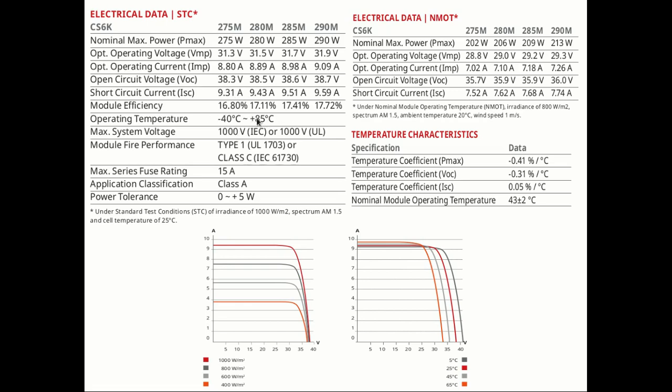Now, some of the other stuff we will not really use. These five are the most important. That is maximum power point, voltage at maximum power point, current at maximum power point, and even more important than that are the open circuit voltage and the short circuit current. We will need these last two, that is open circuit voltage and short circuit current, for determining the parameters of the circuit.